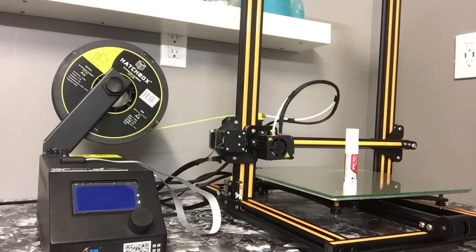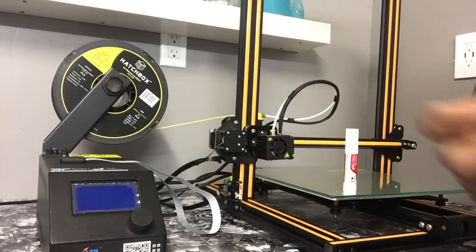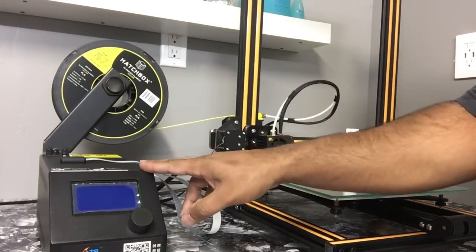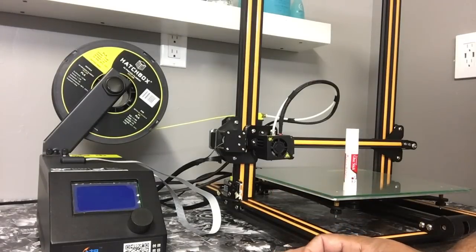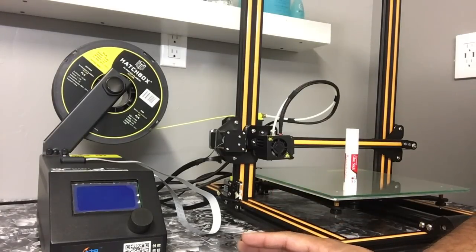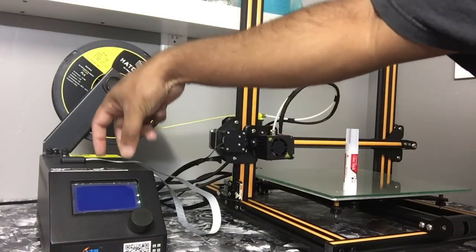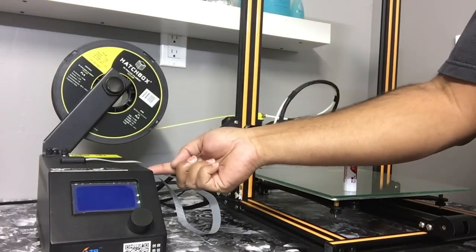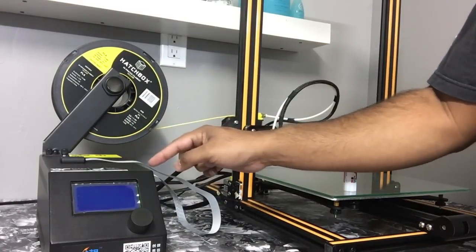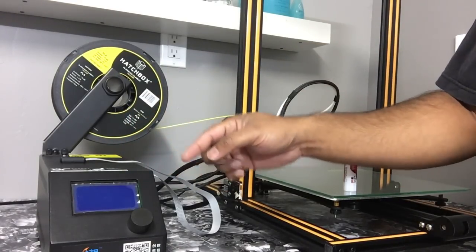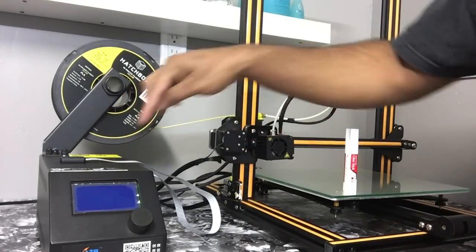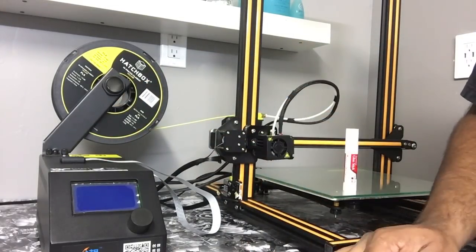Well, let me see what the next one is. Okay, my SD card slot seems a little loose, or it's not reading, or it's wobbly. Most of the time, guys, these printers are made in China, and they're not made, I'm not gonna say well, because they are made well, but because they're mass produced, the machine puts everything together, and sometimes it doesn't do the best job. So your control box might be here, and your card slot is here, and it might be hitting it, and it's in the way, and that's why it's not reading, because it's not going all the way in to read the metal part that sends the information.